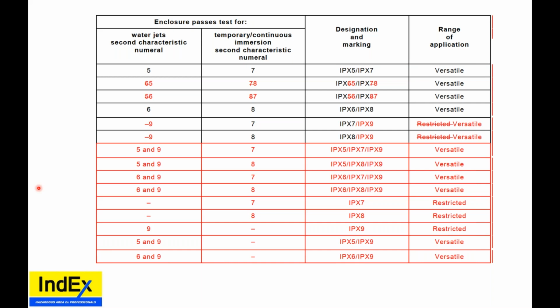As per equipment minimum, IP54 is deemed enough, but they can still test to IP66, or is it a manufacturer requirement? Once again, IP54 is a 10-minute test, while IP66 is only a 1-minute test. The manufacturer can ask for greater testing, greater periods of time, greater pressure, greater temperature.